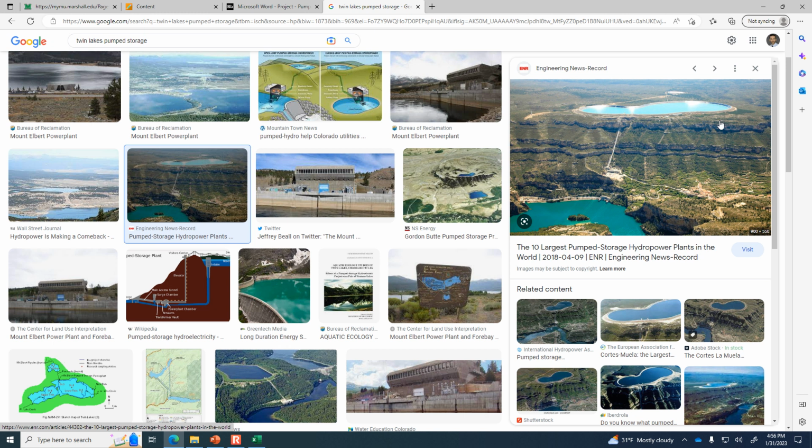Then at night, when they've got leftover electricity from a nuclear power plant, or if they were trying to store power from solar, you'd use the power to lift the heavy weight back up again, because it's consuming electricity to do that. So gravity batteries are similar to pump storage. The advantage is that you're not having evaporation, because you do lose some water, especially in an arid place like Colorado, which is where I see pump storage a lot. It's very dry in Colorado, so they're losing a lot of this precious water.